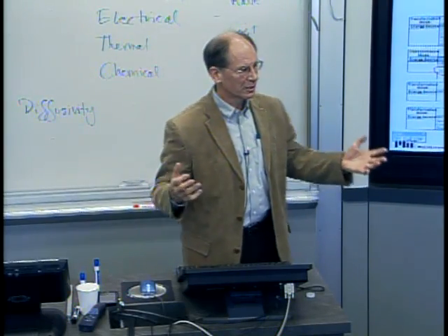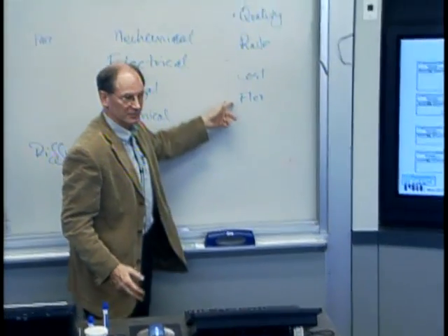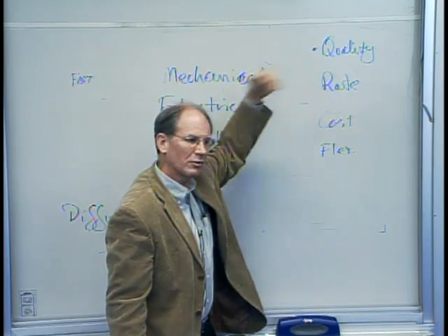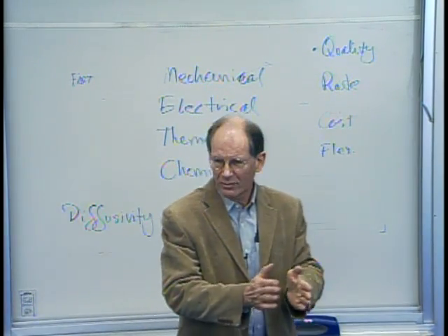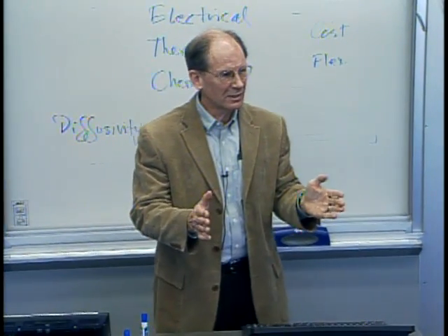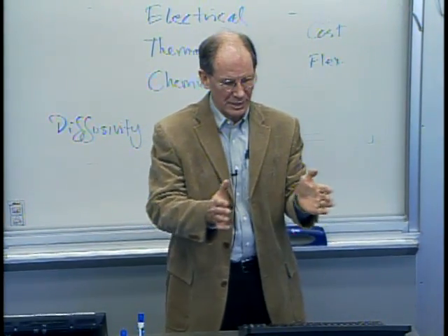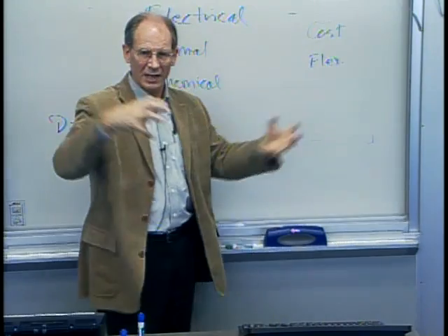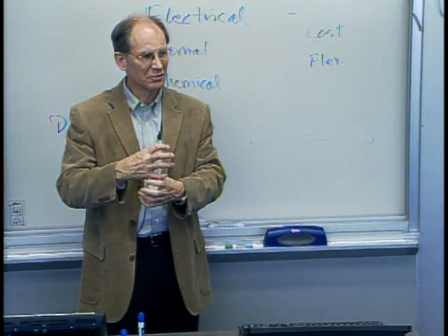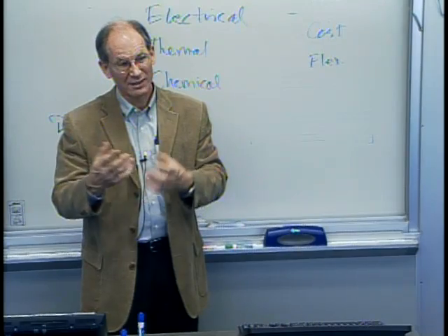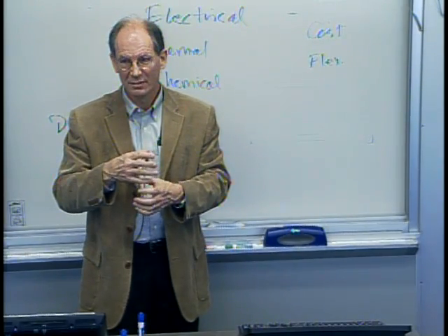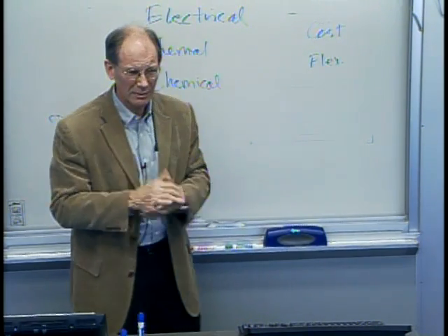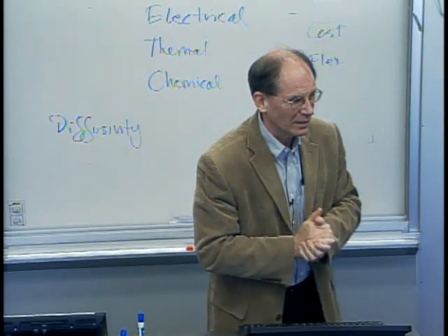So clearly, this serial process is much more flexible. Really great. And I probably can control the quality better because if it's not quite right, I just change the program a little bit, right? If the last one I made was a little bit too wide, I can reprogram the geometry and bring it in a little bit, and it just does it. Whereas if I'm doing hot isostatic pressing, I've got this big expensive tool and it's not quite right, and I can't heat it and cool it like I did with the rolls on the aluminum, I'm kind of stuck with it, right? So why would anybody do HIP when you've got 3D printing?